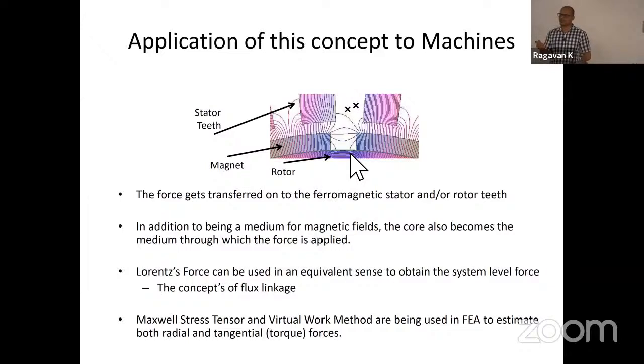If the conductor has a current redistribution because of some other field, not its own field, then we call it an eddy effect, whether it is skin effect or proximity effect. So yes, there can be more proximity effect, and then the heat loss can be higher. But I haven't worked on that. I just heard about such machines and know some concepts to understand them, but I haven't personally worked on them. So yes, possibly there can be more proximity effect in slotless machines.